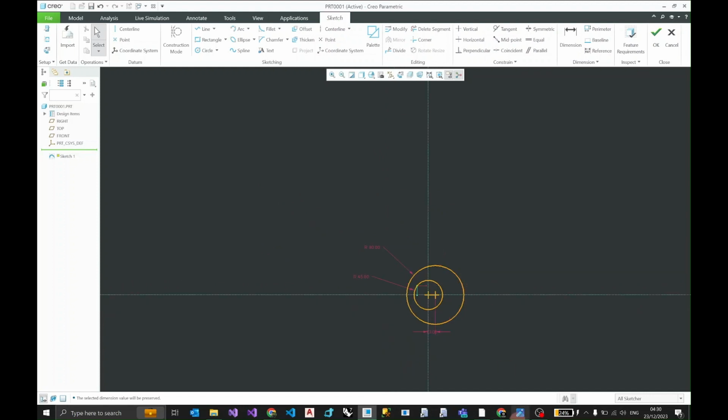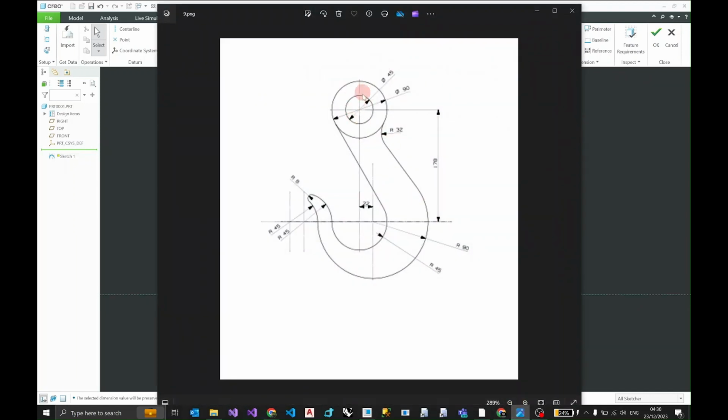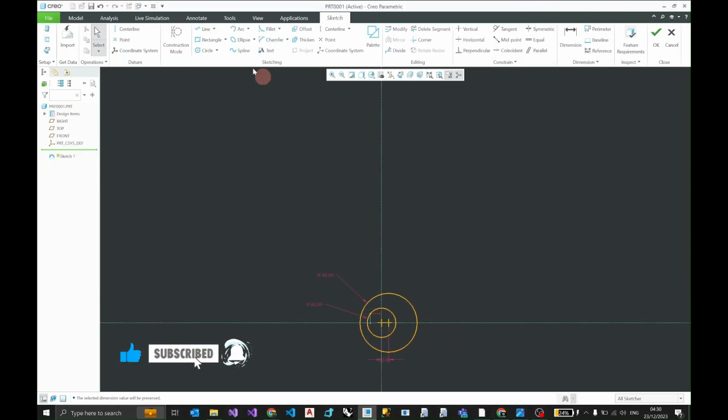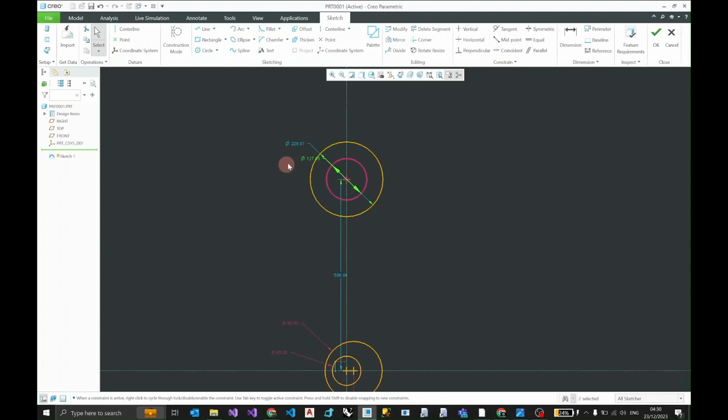So the next thing we're going to do is make these two concentric circles, which are going to be 178 millimeters in the y direction, vertically up. The inner circle has a diameter of 45. You can see this symbol, which means diameter. And the outer one has a diameter of 90. So select the circle, make two concentric circles, and the inner one's diameter is 45.